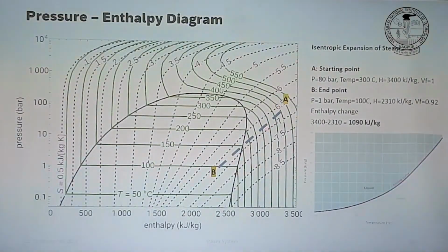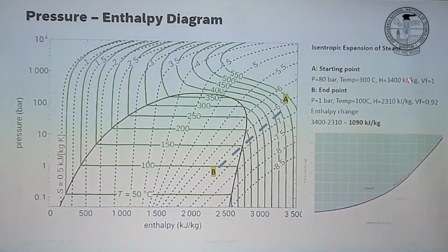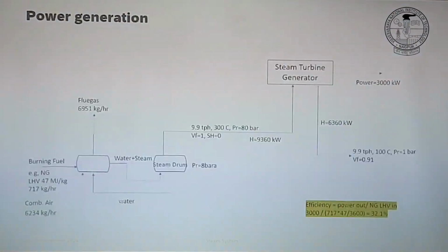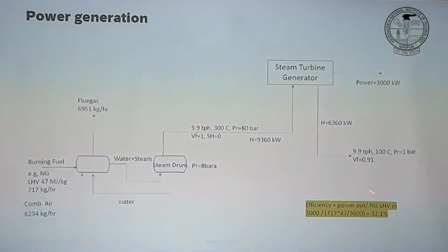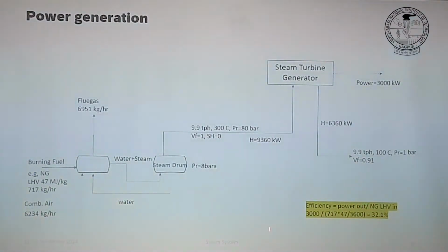So once again on the same diagram, you see we start from point A, even higher pressures, 80 bar. We increase the energy extraction further per kg of steam because we are going even higher with the pressures here. So higher the pressure, we realize that the amount of energy we can extract is much higher for the same amount of natural gas. Similarly, for this amount of power requirement, natural gas requirement will go down. Right? So thereby our efficiency is slightly increased.